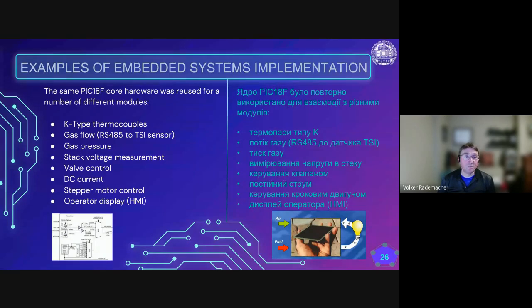All of that can be taken as one group of components and moved onto different modules. For the firmware developer, it is possible to reuse the same core firmware, which, for example, contains the same routines for running the CAN interface, and the same routines for running an RS-232 interface for debugging.